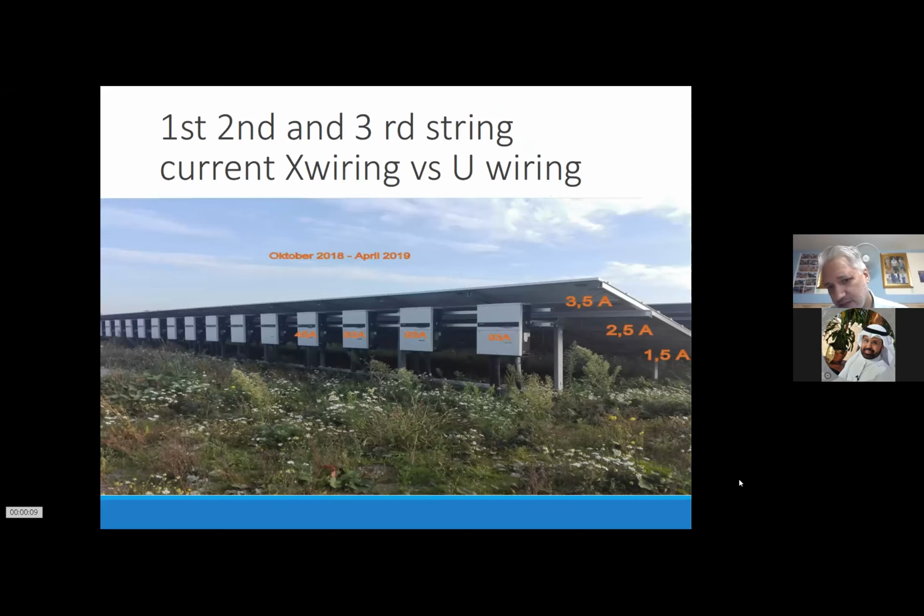That was a sample of these inverters with a row shading, with different scenarios. It looks not too bad actually, but the top one, not shaded, has 3.5 in winter time, while the middle one is 2.5 and the bottom is 1.5. So if you combine that, 3 inverters make 93 to 100 amps, while the one is 45.